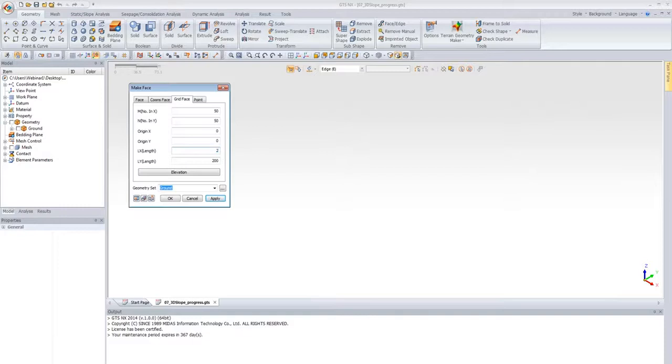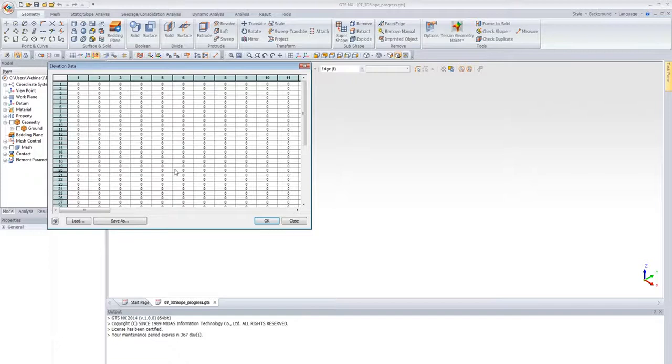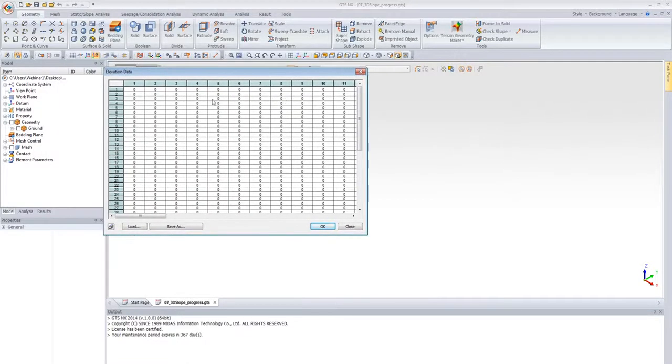And the values that I'm entering are just the parameters of that contour. So let me set this up here, 270, 270. What I'm telling the program essentially is that this particular surface that I'm importing has dimensions of 270 meters by 270 meters, and the increments or grid spacing of each of those elevations is 50 by 50. So it would be 270 divided by 50. I don't remember offhand what that is, but that'll be the spacing. Now let's say I want to import my elevation. This is what my spreadsheet will look like.